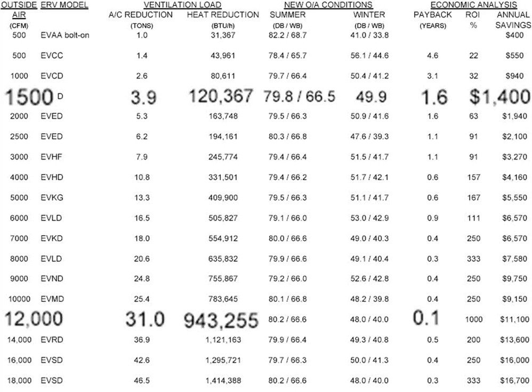That basically means this thing pays itself back in a month. And just to be fair, the reason that some of these are really good, like 0.1 years, 0.3, 0.4, like I said, we're downsizing the rooftop and taking a credit for that. Well, if I downsize your rooftop by 31 tons, I'm probably in a much smaller chassis of rooftop, in the commodity version of a rooftop as opposed to the larger, more custom type rooftop. So I'm going from, whatever, a 50-some ton rooftop down into something that's in the 20s, and it's more of a commodity and hence significantly cheaper. So that's kind of why that works that way. In this case, $11,000 savings.